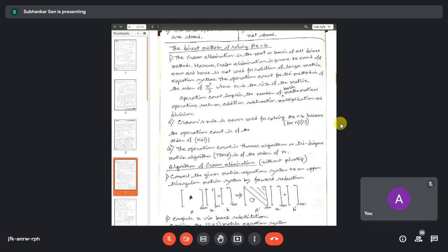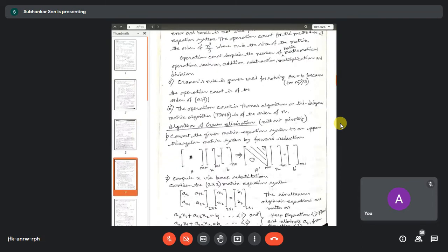So we have given the background. What we shall solve here, we shall not discuss the cases where pivoting is required. Okay. So in fluid dynamics, I have told you before that more or less, a number of times, your matrix is diagonal dominant. It means that if you are using central differencing for the diffusion term, central differencing for the pressure gradient term, and backward differencing or upwinding for the convective term, your matrix will be diagonal dominant. So you remember what I am telling.